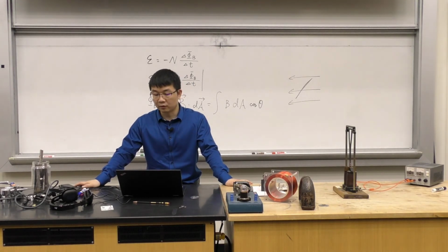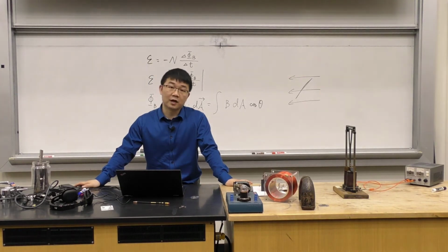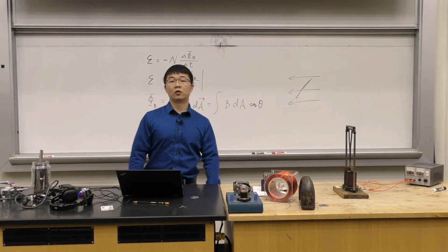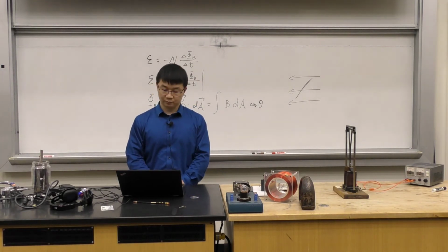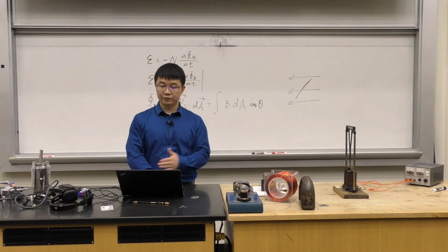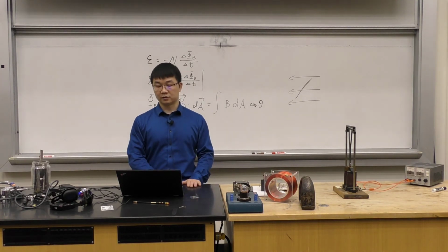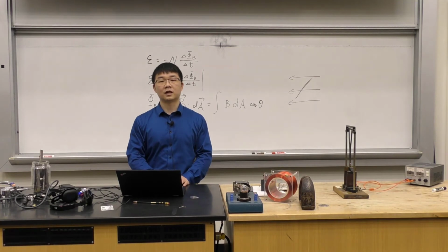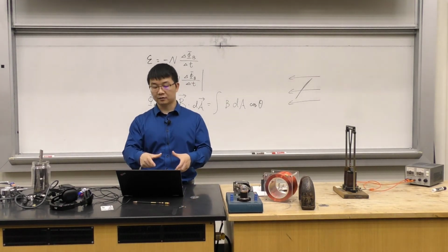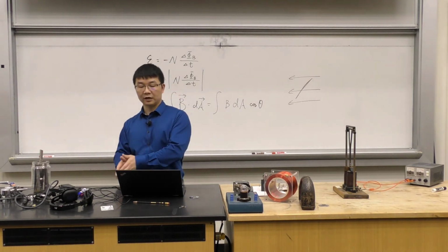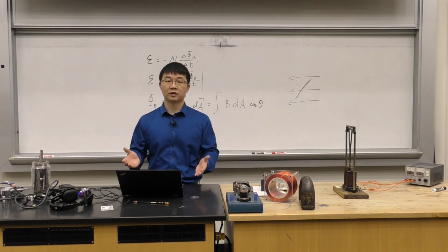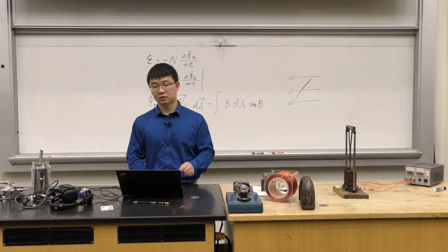And then once the receiver coil gets current, it detects some signal. It has detected there's some metal in your briefcase. And it only works when there's metal in your briefcase. If there's something else, which is not a conductor, then it doesn't matter if the magnetic field created by this transmitter coil is changing or not. It's not going to cause any induced current in anything inside the briefcase, so it's not going to cause any current in the receiver coil. There's no signal. Only if there's some metal in the briefcase.